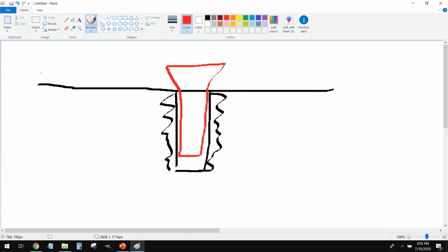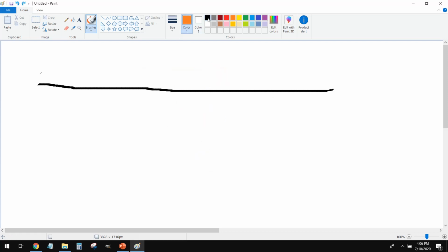And that poses two issues. One, it's not flat, right? So we can't mount anything on top of this. This is going to catch on things. Secondly, this isn't actually holding well because the screw generates its clamping force from this area here and here. And if that's sticking up above the surface, it's not actually doing its job. So what we have to do is when we cut this thread, we have to cut in a bevel like that.